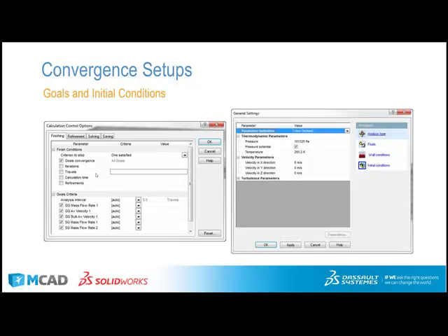For my third one, I gave it goals to acquire and used all of them for convergence instead of travels, iterations, or calculations. For another one, furthering the curve on that, I did a little back of the envelope calculation. I wondered what my average speed in the channel should be given my pressures, and found that I should look somewhere around 8 to 15.